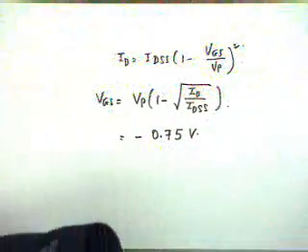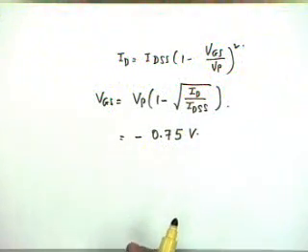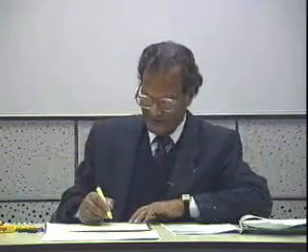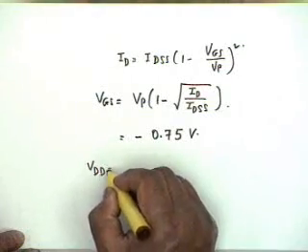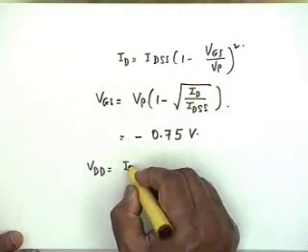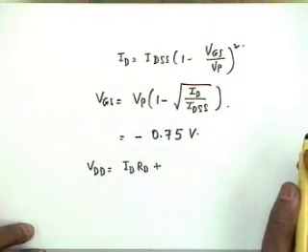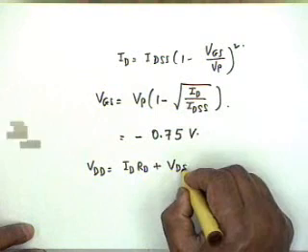All right. So the design means what? You have to fix the supplies now, VDD, VSS, and what else? In the simple differential amplifier, R sigma. Now, for VDD, you notice that VDD is equal to ID RD plus VDSQ, which is given, the operating point is given.